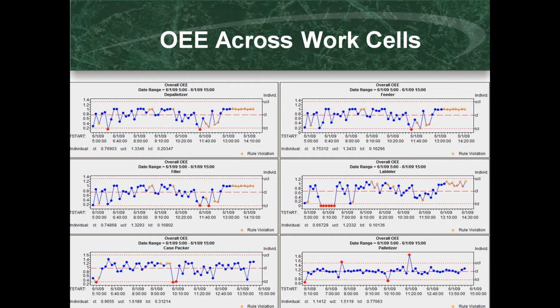When you have these statistical outliers that are taking your OEE close to 100%, you want to know what is going on at this period of the shift that you wish you could replicate for the rest of the shift. What's happening at these lower control limit breaks that you want to reduce or eliminate so that you can bring up your calculations? If you have an automated data collection system, you'd want to dig into the details of the events that took place when these lower and upper control limits were breached. What happened on the line at these points in time that we can eliminate in the future?